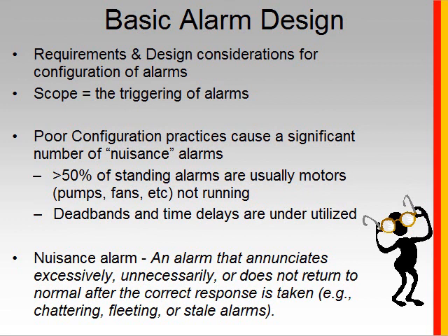Some of the things that are included in basic alarm design is making sure that alarms are not created just because equipment is off. You only create alarms if the equipment is off and that's a problem, or that's not the situation that's supposed to be.